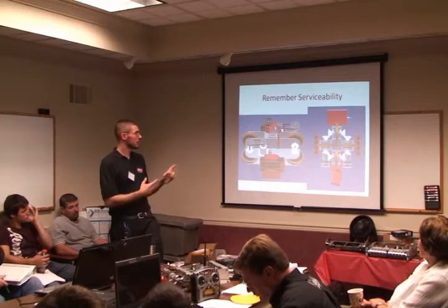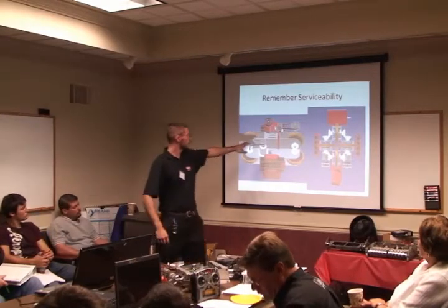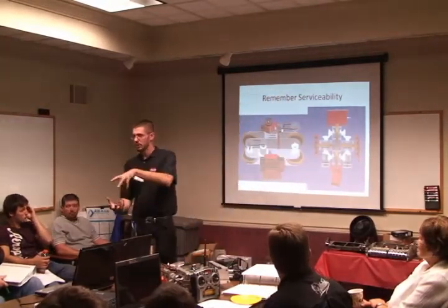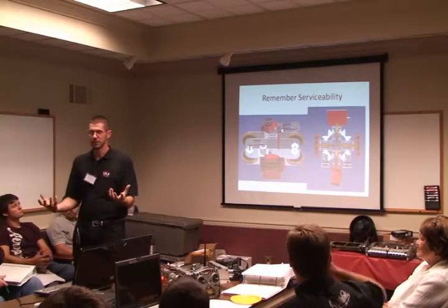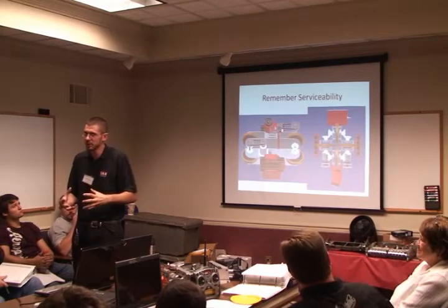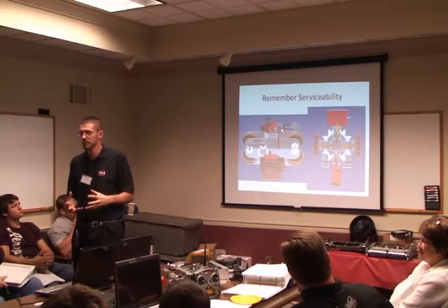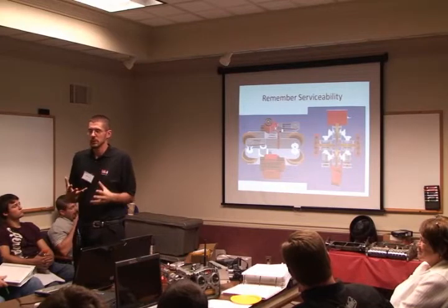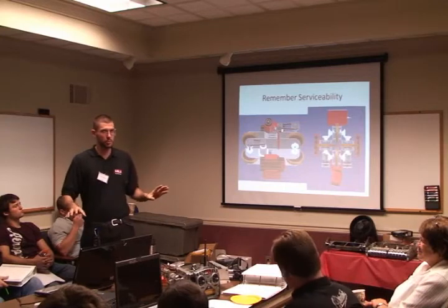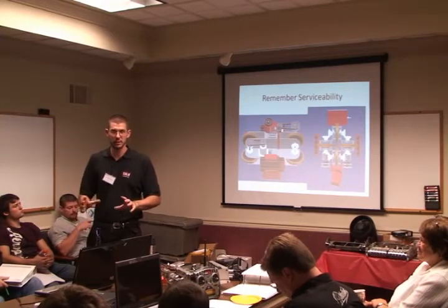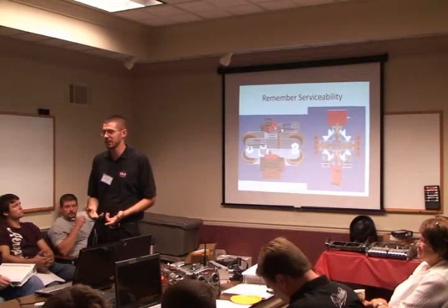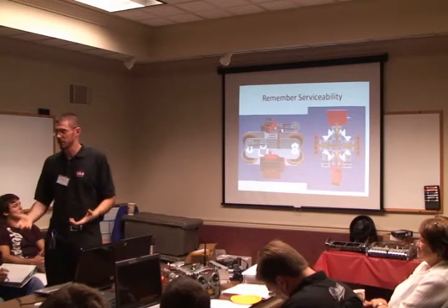But as you can see, there's so many bolts that got to go into all the components to hold it together. You see all the spacers. You have to build it in two halves, and should something break, you have to very carefully take it apart. Everything bolts together so hard, it takes like 3 hours to take this thing apart to service it. So we went with a very simple design, very rugged. It goes up and down the rope, no problems, works flawlessly. But should we ever have to fix it out in the field? There is no fixing it in the field. You have to do it in the lab. You have to do it in a workshop.